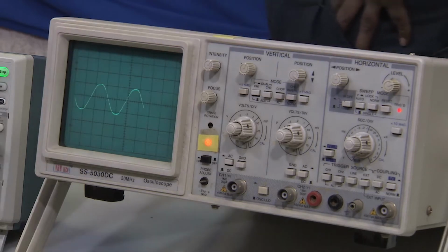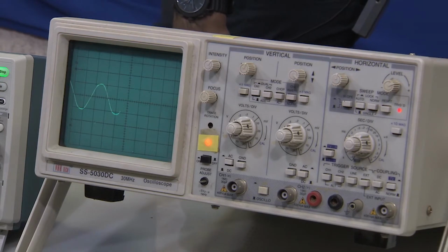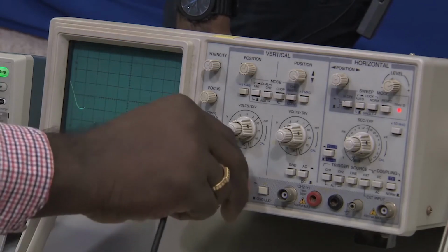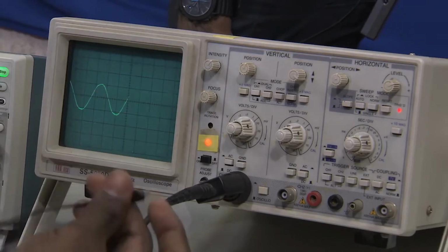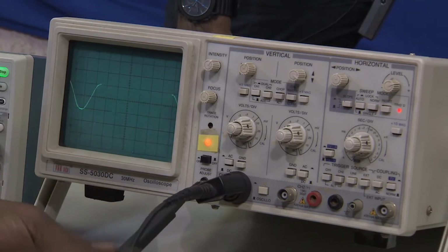Now, you have two positions in vertical, the first position is for channel 1, the second position is for channel 2. So, there is channel 2, there is channel 1. Now, we can change the volts per division. So, let us connect another probe to this oscilloscope. Here also we can do the testing of the probe. So, we are now connecting the probe, as you see the probe is connected, okay. Now, we have to test the probe. There is a probe adjust, you can just connect it there, and another one would be at ground.